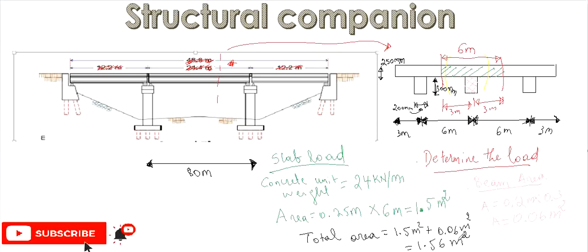Now to determine how much load is coming, because they say the unit weight of concrete for each meter. If I have 1 meter of a slab made of concrete, remember that the beam and the slab both are made of concrete. It was 24 kilonewton per meter cube. I forgot, sorry. So 24 kilonewton per meter cube is the unit weight of the concrete. Remember it is a uniformly distributed load, because this load here is continuous. It is the same load throughout the length.